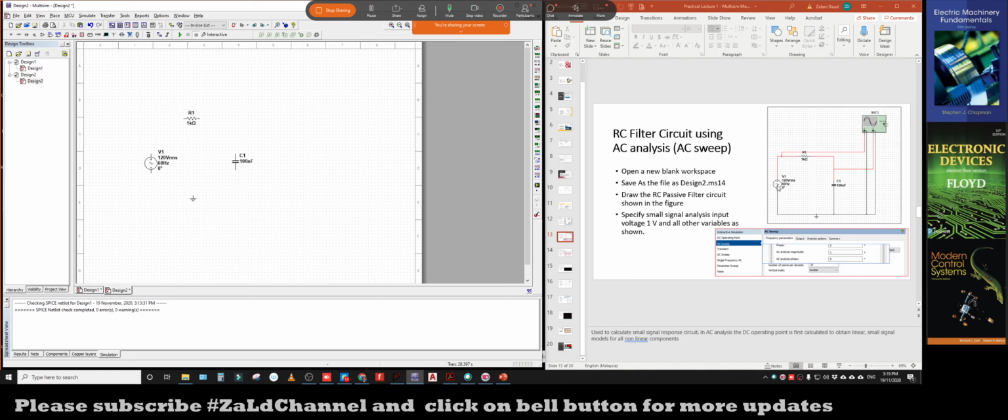Now make sure that the value of each component is correct: V1 is 120 VRMS, 60 Hertz frequency, 0 degree angle, then the 1 kilo ohm resistor, and 100 nanofarad for C1. Just double check the component values. Next, do the wiring as usual. Connect each terminal to wire all of the components and complete the circuit like that. So I have finished drawing this RC filter circuit with the AC source here.